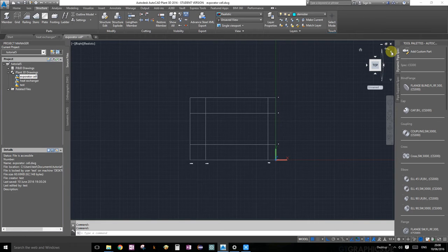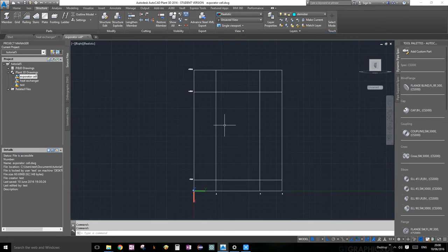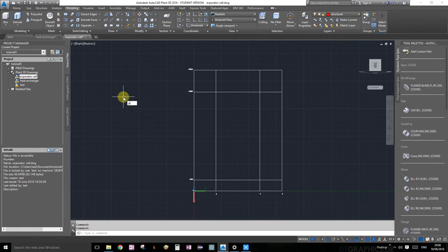Okay, I don't like that. I'm going to turn it around. Perfect. So we're going to create another polyline, unfortunately, but that's what we have to do. Make sure you're on the structural plane again, and let's go back to modeling and type PLINE. Press enter. Nope. Whatever that shows up, I do not know why. Nothing's showing up. I'm pretty sure it's drawing stuff, but nothing is showing up. I'm not sure why. So let's start PLINE again.